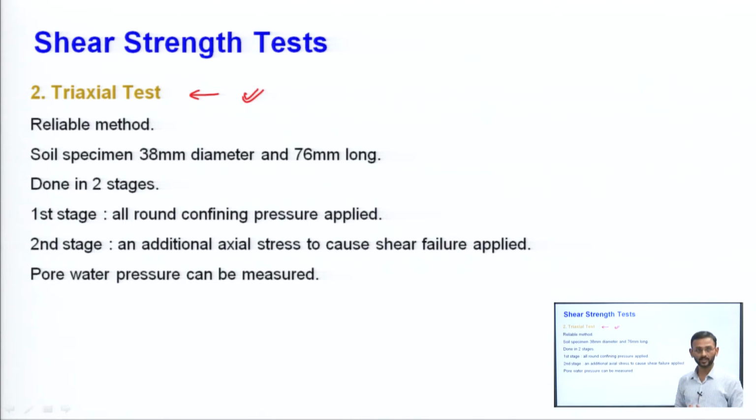This is a very reliable method, the very first point here, that is an advantage, because we are trying to control the pore water pressure. When we can control the pore water pressure, we can simulate the field conditions in the lab, and when you can correctly analyze in the lab, then with very good approximation you can apply it in the field.